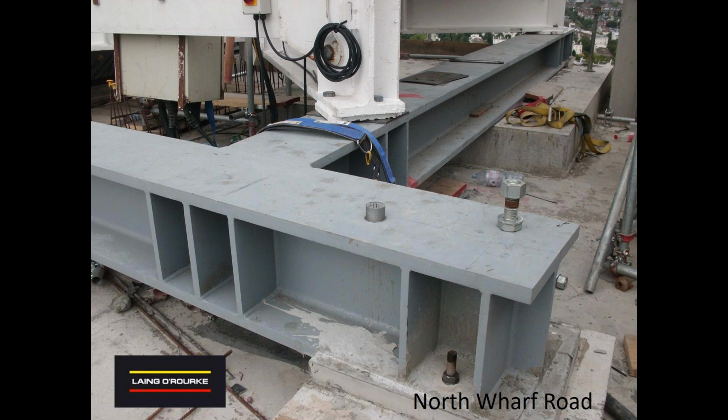Checking for the deflection of these beams is key, because if the grey gridage beams start deflecting, that will cause the crane to lean. So the calcs are run through, finite element models prepared, and the potential worst case lean verticality tolerance of the crane is checked and deemed to be acceptable or not. If it's not acceptable, the gridage will need to be increased in size.